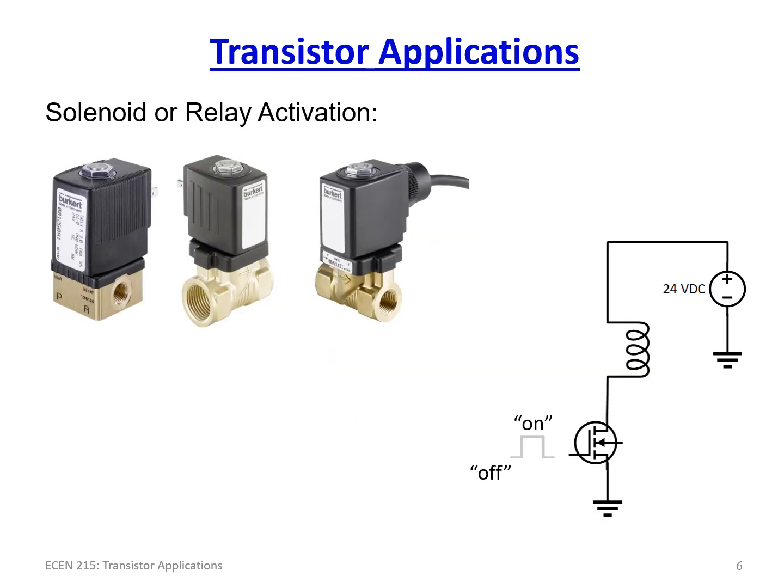Another place where transistors are heavily used, again, is in solenoid and relay activation. Again, in a mechanical system, you're going to have control valves to move fluid, to move air in pneumatic systems. In fact, I was just working on a project a few months ago for a pneumatic air system for Texas Instruments on one of their production lines. And this is exactly what we had. We had an air solenoid, and I had to actually turn on and off a solenoid inside here. So there's a magnetic coil here that would actually cause this valve that's mechanically in here to activate.